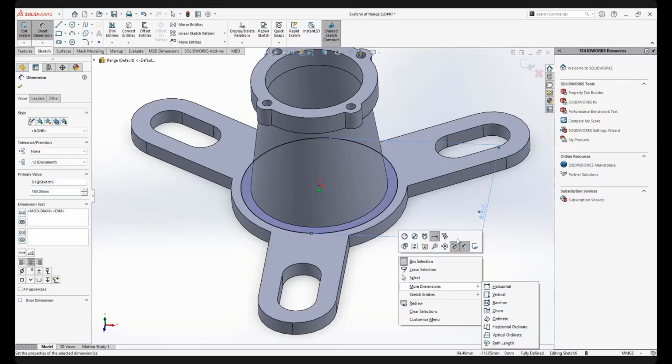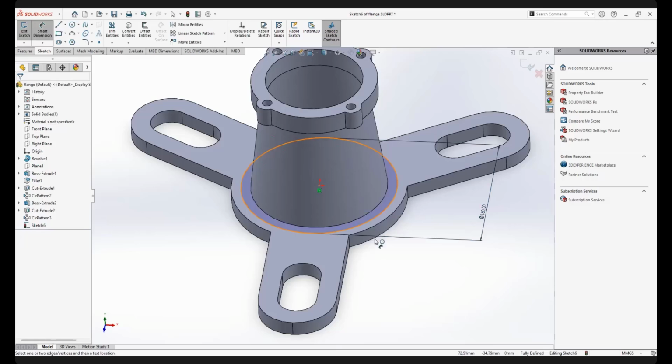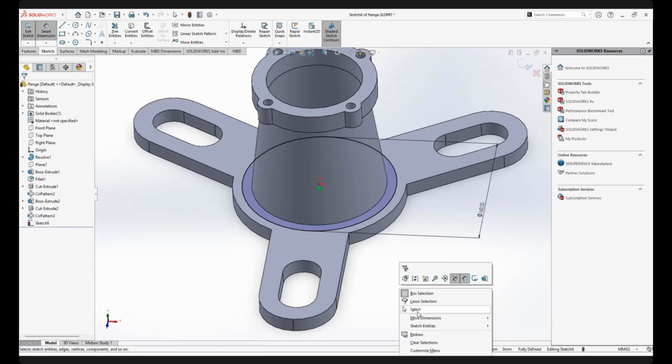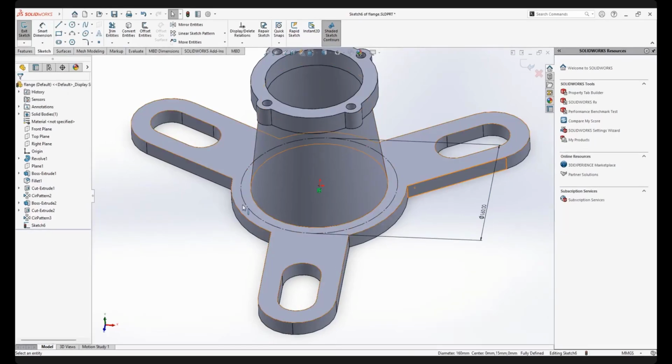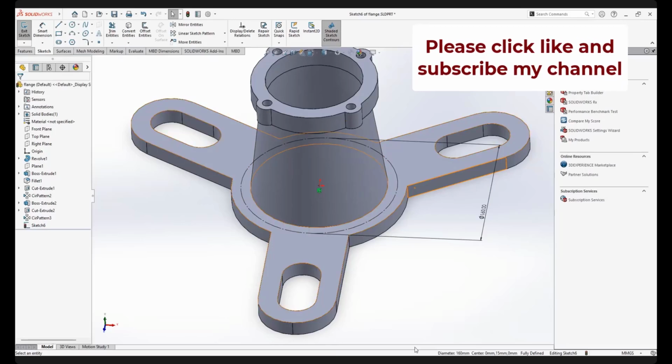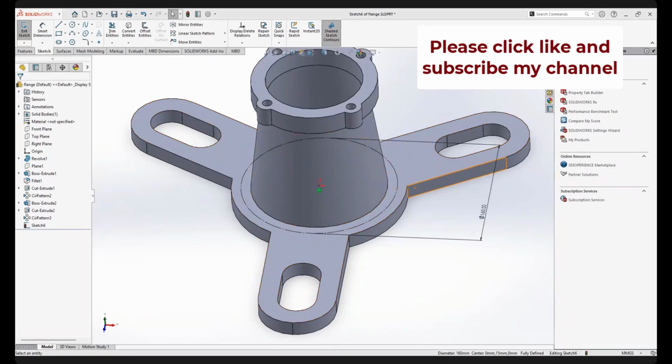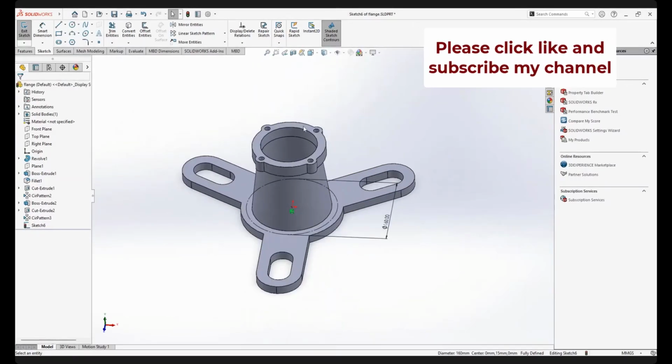What I need to mention, this circle is not solid line. You select this circle, the icon here, construction geometry, make it center line. Then you position how to position that drill through hole, you figure it out, based on the angle that I just showed you. Okay, class, I stop until here. So this will be your second assignment.